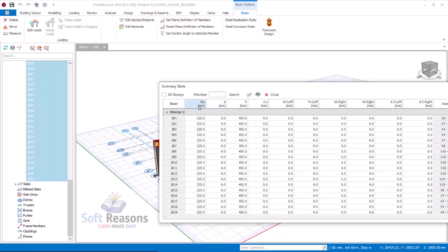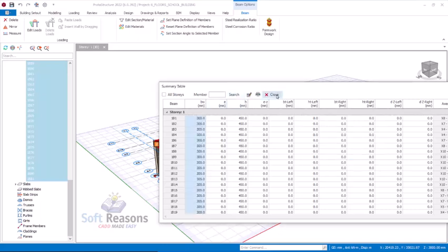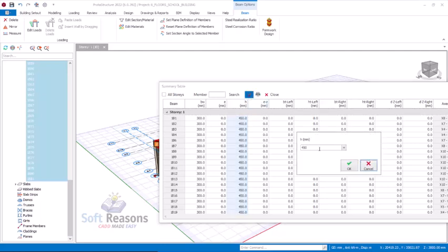So where you have 225 right there, selecting these provisions and then column wise edit. Here we change it to 300, just like this. Click on the OK options. Then for the depth, we will change that to 500.